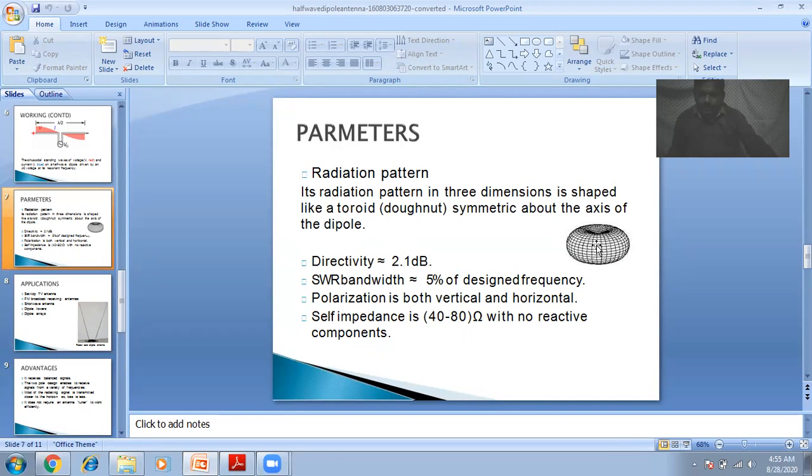That means if you cut this radiation pattern horizontally into two halves, only the upper half is seen physically. Since the radiation pattern is half that of the dipole antenna, automatically the radiation resistance is also half. In that way, the radiation resistance of this monopole antenna is seen as only 36.5 ohms.